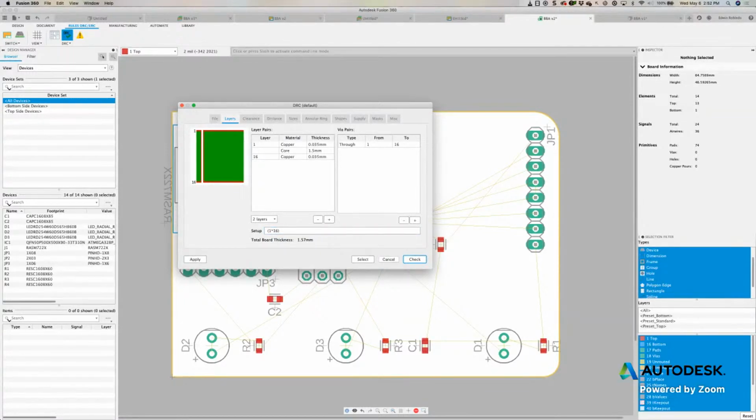Boards are always going to work in pairs. If you look at a circuit board, you have your top layer and you have your bottom layer. In this scenario, we're only using a 2-layer board. But if I wanted to go to a 4-layer board, and yes, in case somebody asks, can I work with 3 layers? You can. But no matter what, the board house is going to work with 4 layers. So it's just not going to put any information on that other layer,